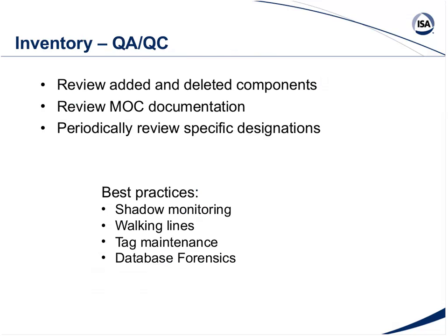You want to look at how my best practices are for my folks that are out there monitoring. You want to look at your added and deleted components. That's a good place to do database forensics. Go in and look at how many components were added over the last week, or how many components were added over the last 6 months. So those numbers make sense. We want to look at our MOCs and have a way to go back and look at that MOC. Does the number of components added or deleted match the type of work that was done in the MOC? That's another place to look.